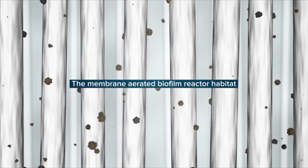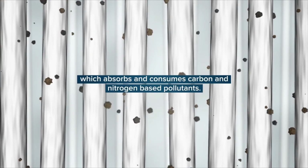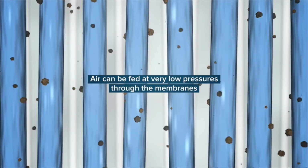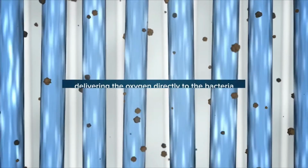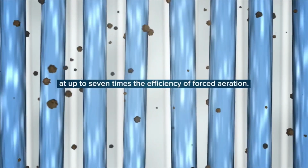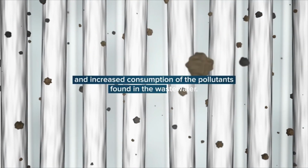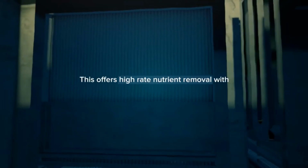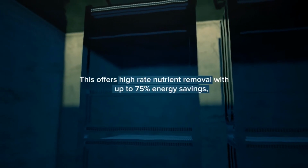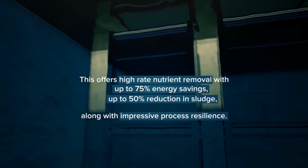The membrane aerated biofilm reactor habitat creates an ideal environment to support a robust biofilm which absorbs and consumes carbon and nitrogen-based pollutants. Air can be fed at very low pressure through the membranes, delivering the oxygen directly to the bacteria at up to 7 times the efficiency of forced aeration. Bacteria now have the optimal conditions for growth and increased consumption of the pollutants found in the wastewater. This offers high-rate nutrient removal with up to 75% energy savings, 50% reduction in sludge, along with impressive process resilience.